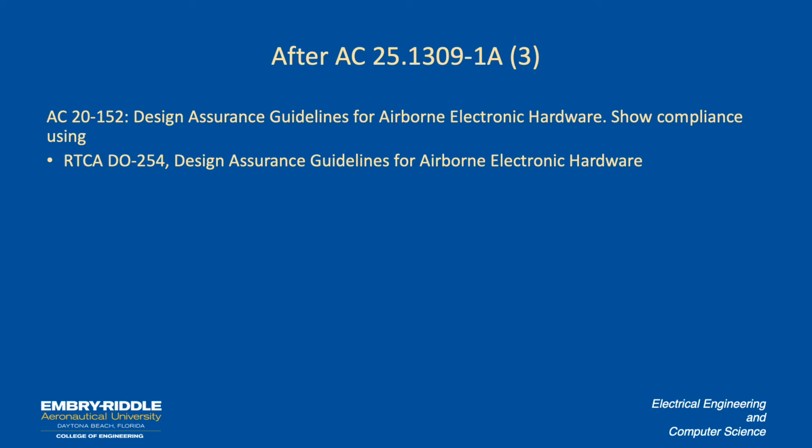On the hardware side, Advisory Circular 20-152, which is called Design Assurance Guidelines for Airborne Electronic Hardware, says you can use RTCA Document DO-254, Design Assurance Guidelines for Airborne Electronic Hardware, to demonstrate compliance for what's called complex electronic hardware.